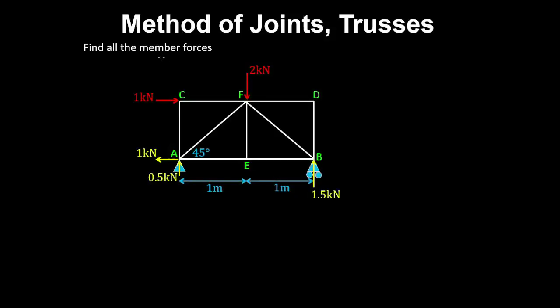The method of joints is useful for finding all member forces in a truss, and is best illustrated with an example. And first you find the reactions, and then take an equilibrium of the joints strategically to first identify the zero force members. So the member forces going through joint D are in member DF and BD.